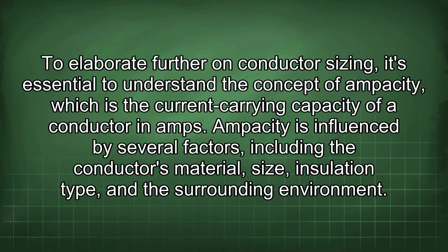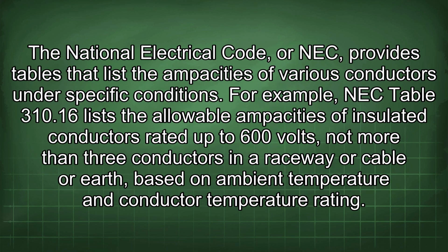To elaborate further on conductor sizing, it's essential to understand the concept of ampacity, which is the current carrying capacity of a conductor in amps. Ampacity is influenced by several factors, including the conductor's material, size, insulation type, and the surrounding environment. The National Electrical Code, or NEC, provides tables that list the ampacities of various conductors under specific conditions.